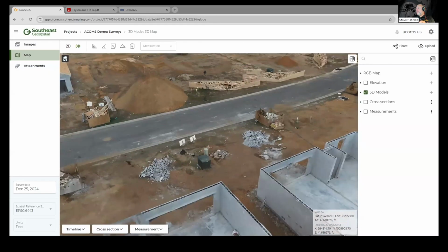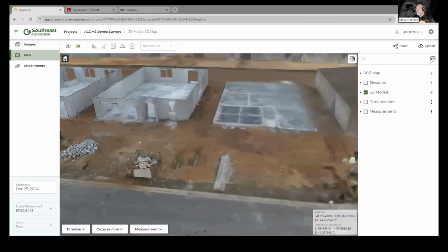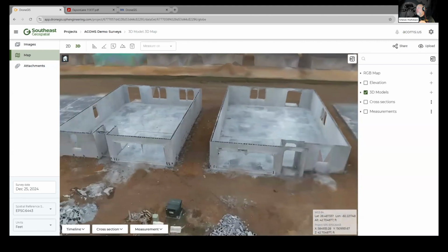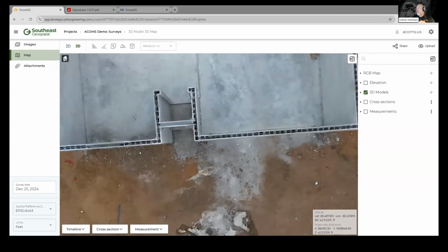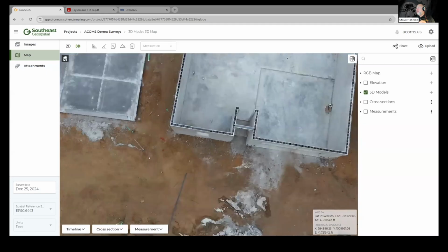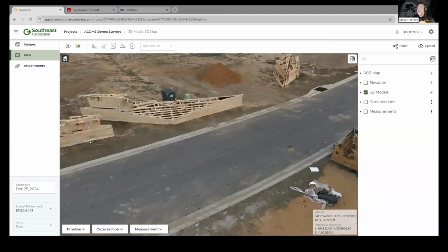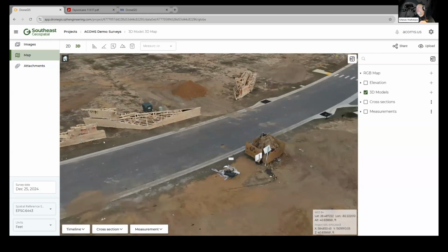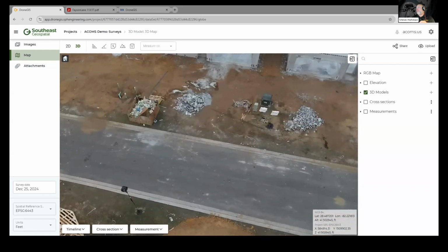He said, now turn around and look at the houses. You got one with a pad, two with a pad. You've got two that are ready for trusses, but here in Florida, that wall is not capped, it's still open, which means the inspection hasn't completed yet. Therefore, these trusses are early, and not only are they early, but they're sitting on the ground, which means that if there's any moisture in the ground or if it rains, they're going to absorb that moisture, they're going to get wet, could lead to mold issues. So now you have a logistics problem with the delivery of these trusses and how they operate.